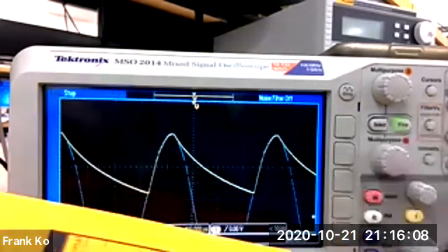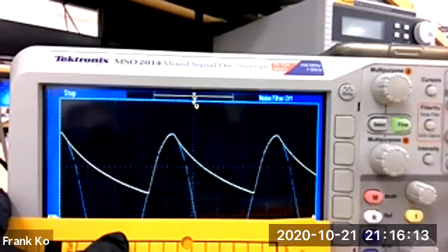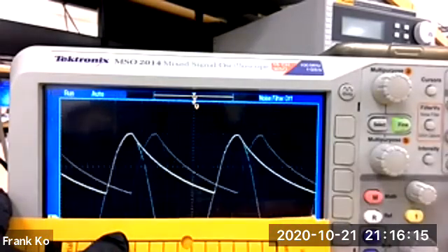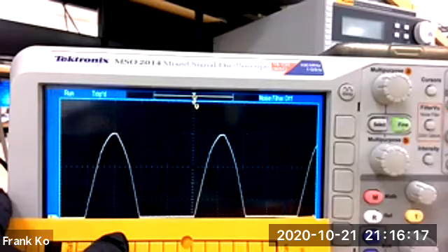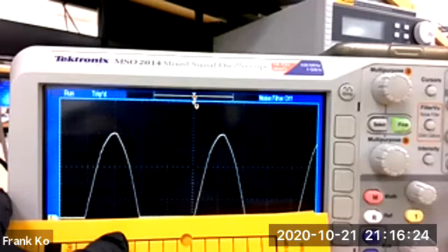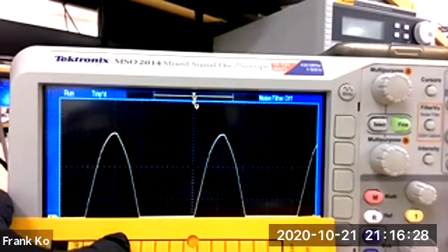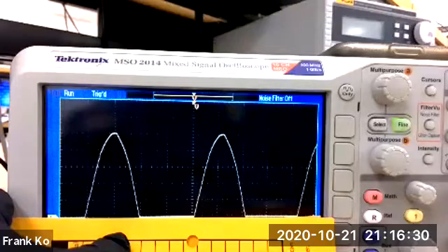So what happened as a result? What happened as a result, look at this again. I'm going to put this in the run mode, disconnect my cap. Everybody see half wave pulsating DC? Where is my zero on the yellow waveform? My zero on the yellow waveform is matched with the zero on the blue waveform. Where my paper border is set up, yes?